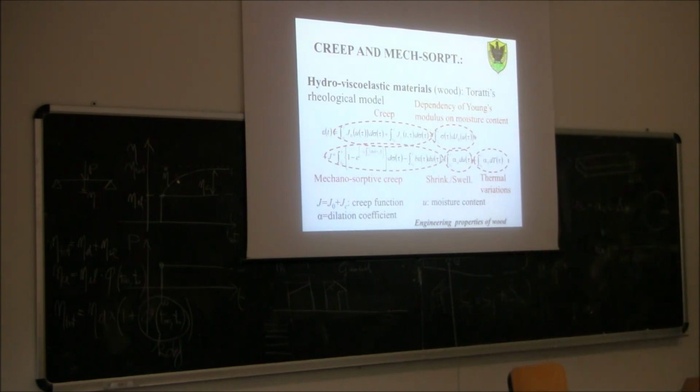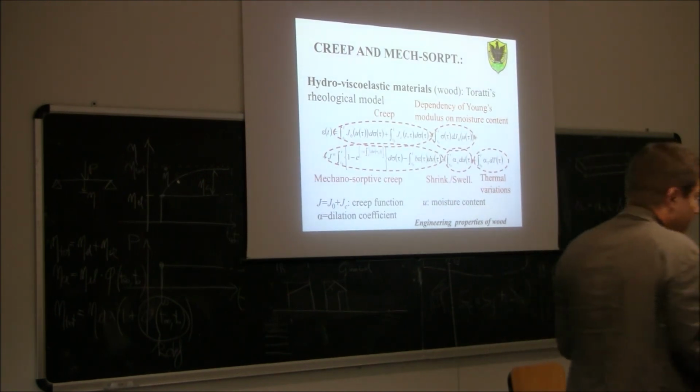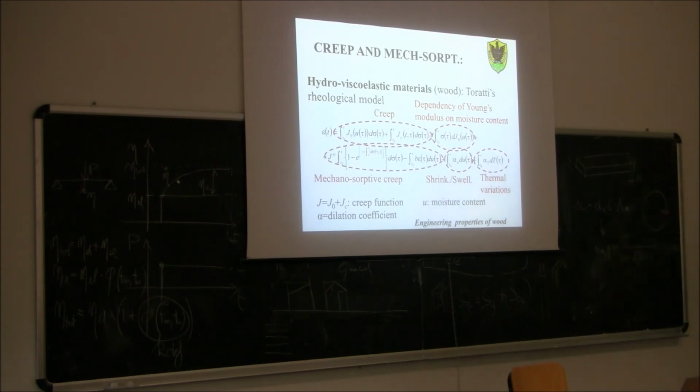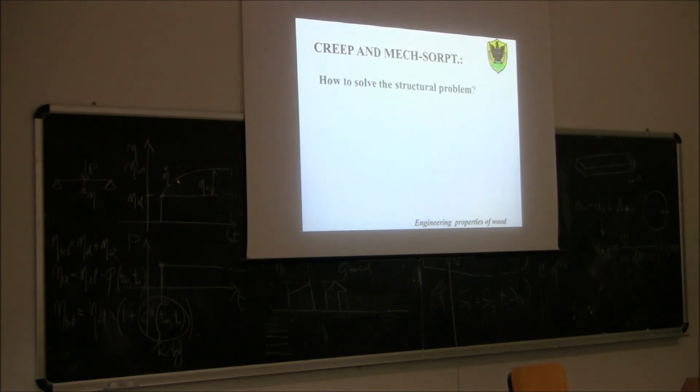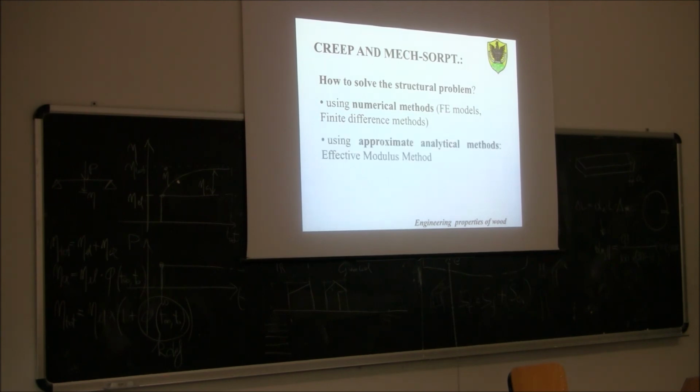Of course, we are not interested in this kind of complex equation. We are interested in being able to design a structure. So some simplification of the math. What kind of simplification? If we want to solve the structural problem, we should use a numerical method, finite element models, but as a designer, the most useful thing is to use an approximate analytical method. In this case, we use what is called the effective modulus method.